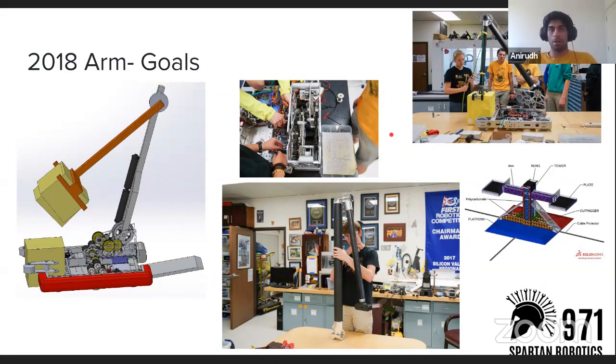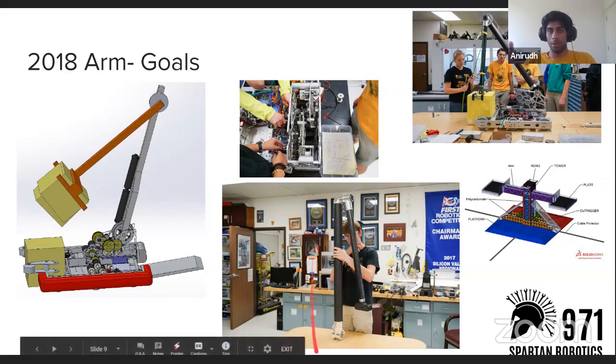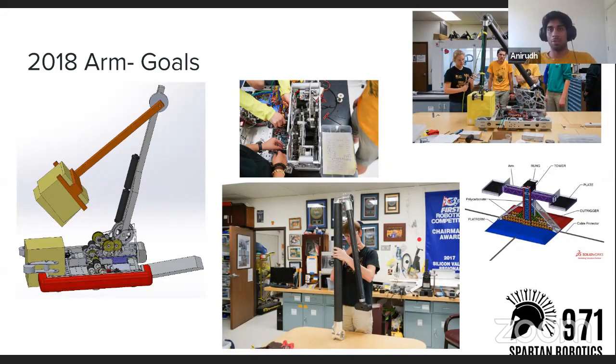This is why for our placement mechanism of cubes, we decided to use an arm, a double jointed arm specifically, because we could reach inside the scale using a double jointed arm. You can see a picture in the top right over there. The double jointed arm has two bits, or two arms essentially. Both of them are carbon fiber pieces, and the bottom arm is attached to a sprocket at the very bottom in the gearbox. You turn that bottom sprocket and it turns the bottom bit. And we have string that turns a pulley at the very top of the arm, which turns the second bit of the double jointed arm. It gets the name double jointed because there are two joints on it.